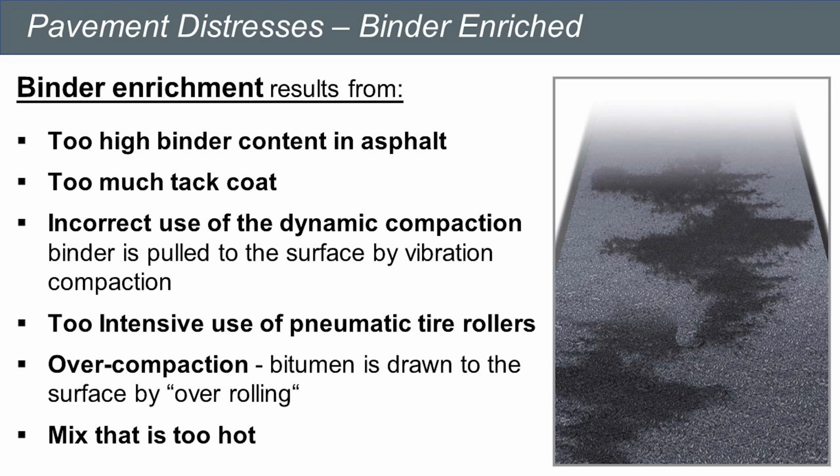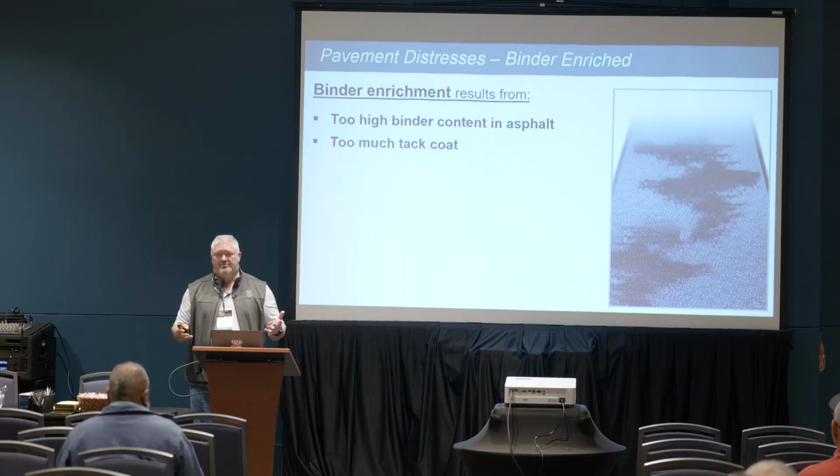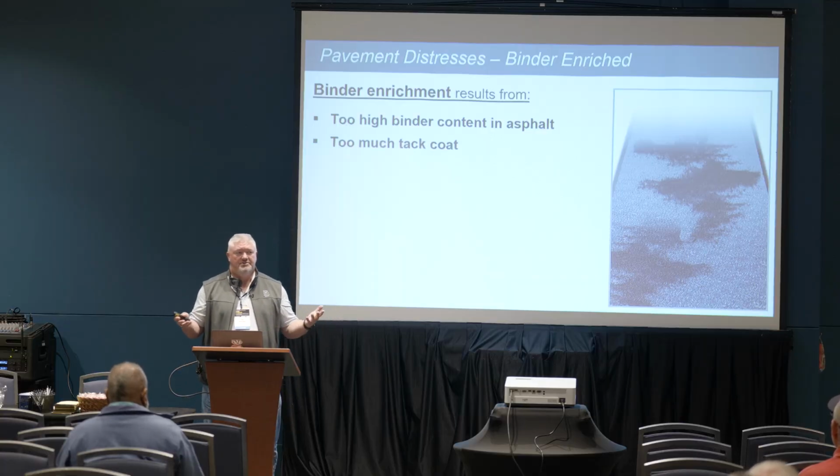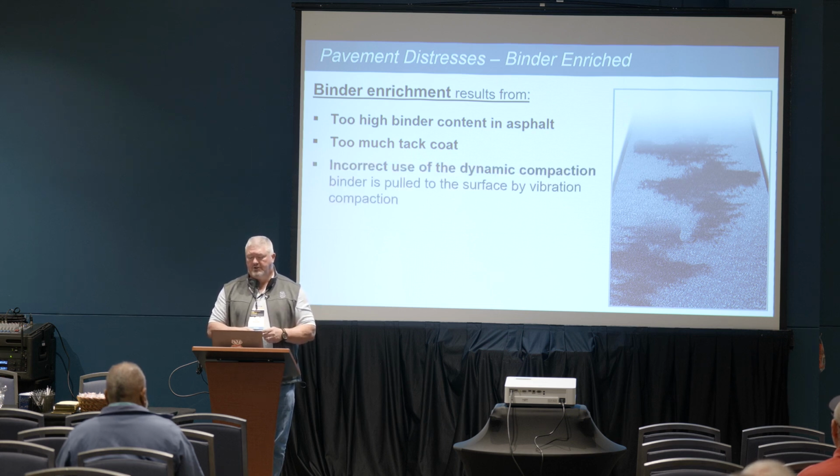Binder enrichment, or I call them fat spots. Too high AC content in the mix. Too much tack coat, and tack coat is another whole presentation. I think there's one on that this afternoon. But tack coat is very important when it comes to bonding the layers together.